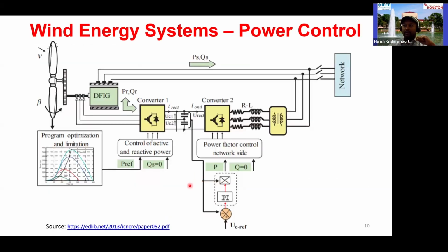Now, a quick thing about wind energy systems as well. Again, wind power. Of course, when the turbines go around, they create a rotating motion, and this is a doubly fed induction generator, and this is a gear system. The wind turbine rotates relatively slowly, and the gear converts it into a fast rotating speed ratio, and that drives a generator. And please remember, this is a question that I have been asked several times.